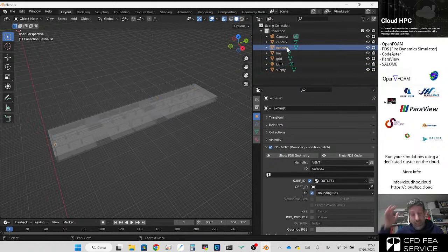Mis-flow that will always exist, also in real life. Usually we don't have exhaust fans and supply fans providing exactly the same flow rates. The flow rates are slightly different, and they are balanced by openings, ramps, grids, or other windows which are open to the atmosphere.